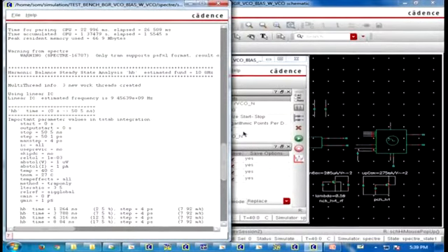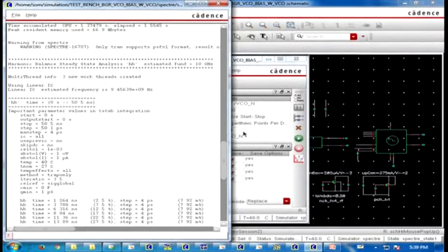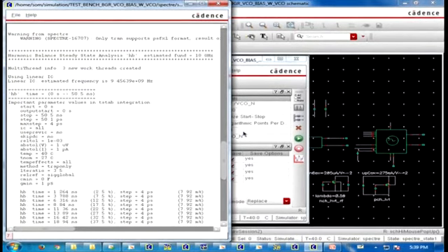And next, after the pad, there is a bonding wire. Is it off chip or on chip? The bonding wire, I showed the rectangular pad, and the pin that is out, the ceramic chip is there, but in the package itself, the bond wire connects the pin and the pad. So you cannot see it, but if you open the black IC, you can find those bond wires.